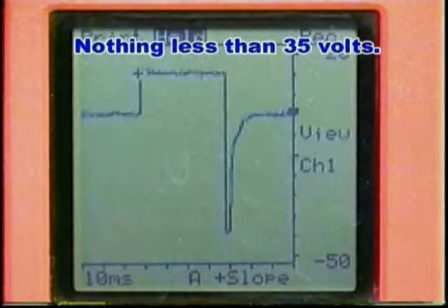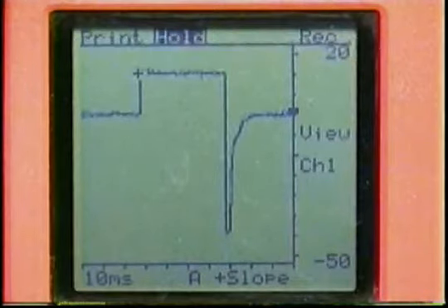If the injector coil windings are semi-shorted, the spiked vertical line is going to be much lower than 35 volts. Next we see the injector pintle closing, or the actual physical closing of the injector pintle. This is not the point of electrical turn-off, which is denoted by the vertical line preceding it. It simply takes the injector pintle a few milliseconds for it to close completely.